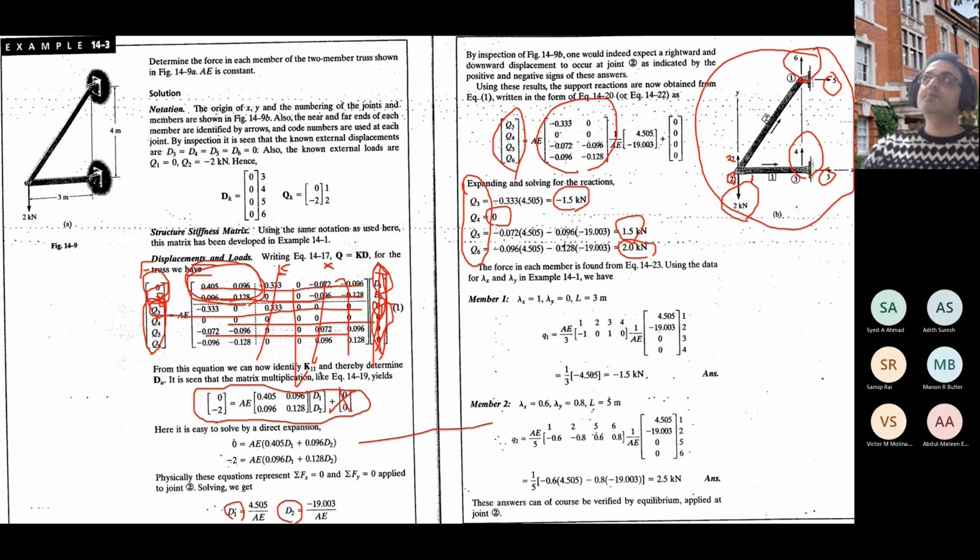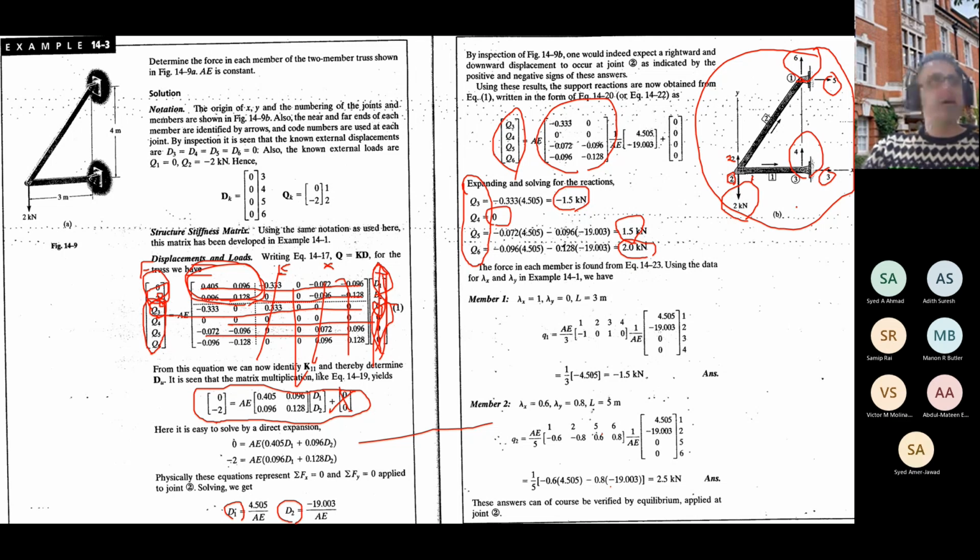So if you test, validate, verify your 3 equilibrium equations for the whole structure when you come up with the support reactions, it's a kind of improvement that you haven't made any numerical error in your calculation, so you can see that your calculation is valid. So